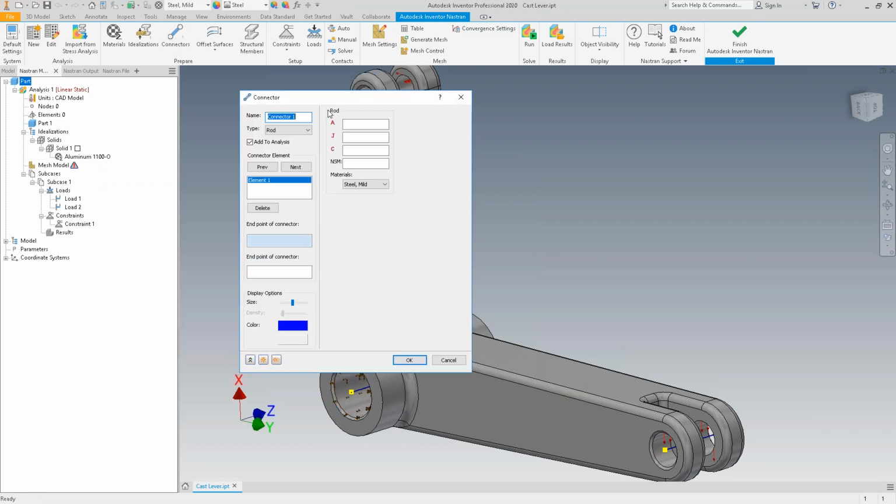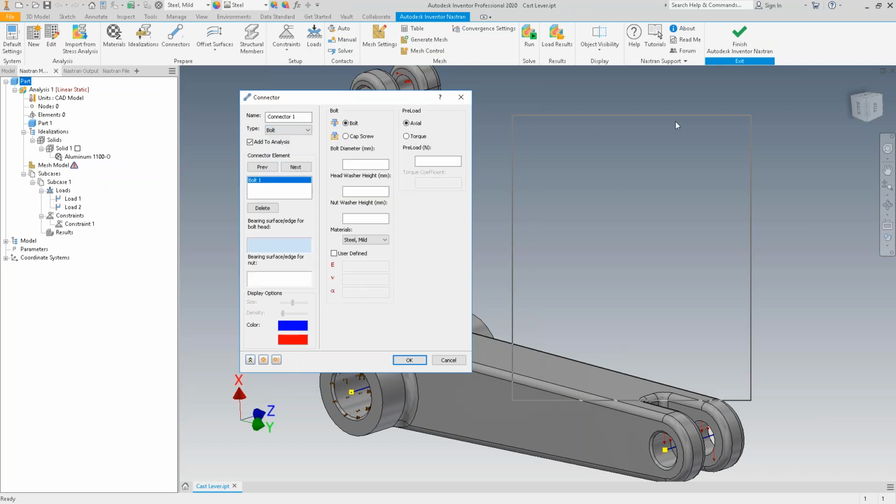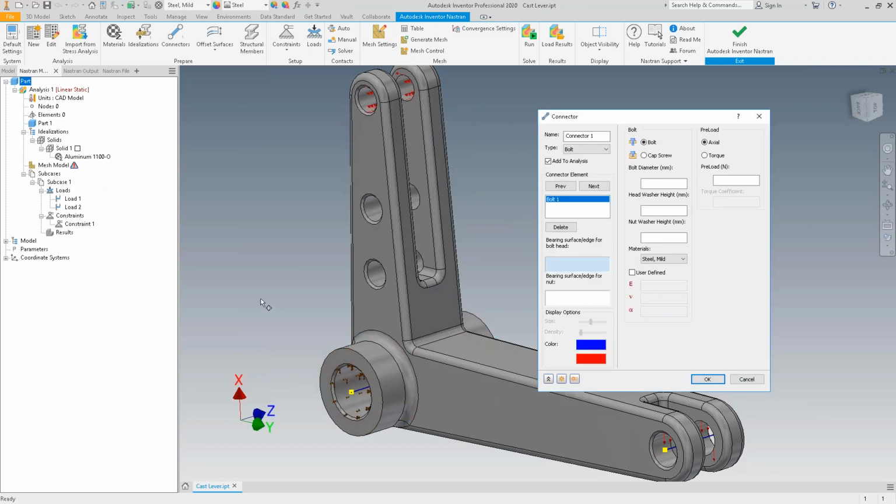This is an advantage if we have something like a bolt connection, for example, that's going to be holding this on that center pivot. You don't want to model a bolt and a nut and a washer, or if you do, you don't want to include them in the analysis. They tend to complicate the math and can skew the results sometimes. And we can look up material properties and behaviors of bolts and nuts and see how they're going to perform under stress loads. So we don't need to plug that into the analysis. We need to look at everything else.